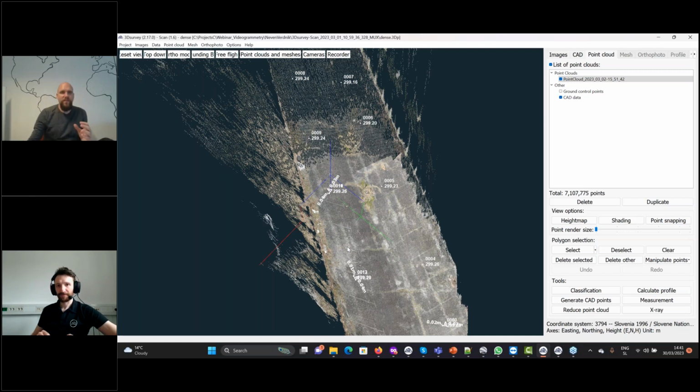Okay. So the RTK device reports accuracy of around 1 centimeter most of the time. That's a very highly accurate GPS. From my experience, even the big GPS's accuracy will usually be around 3 to 4 centimeters. So I believe that accuracy is calculated basically that the GPS measures its position for a while, and what I think happens is it takes its position and calculates the standard deviation of the last few positions, and it reports that as its accuracy.